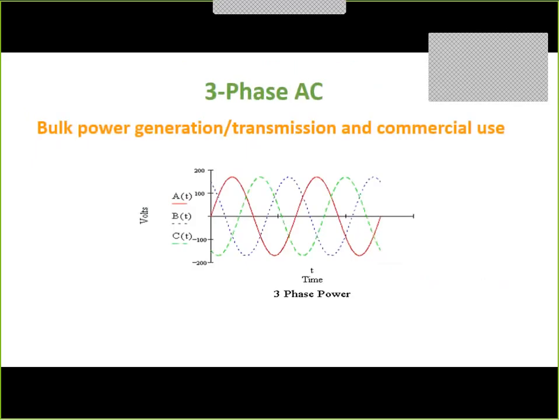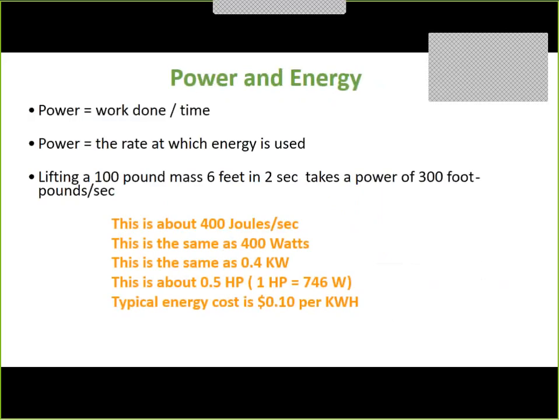3-phase, we use 3-phase, not single-phase. Single-phase has a pulsating power. If you multiply the voltage times the current in time, you get a double frequency pulsation, which will ruin a shaft. It'll break it. So we don't use single phase that much. We use 3-phase because with 3-phase you get the pulsations canceling out so that the total is a constant. Nice, smooth torque.